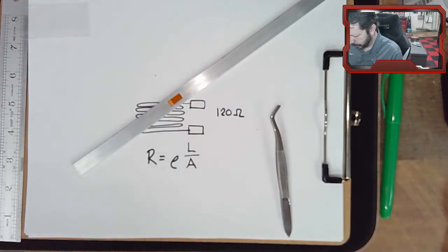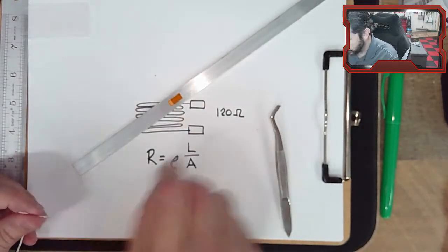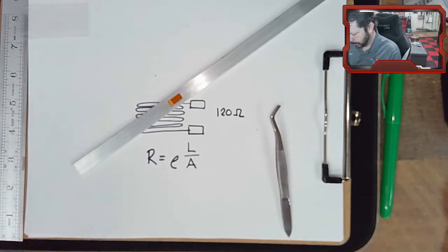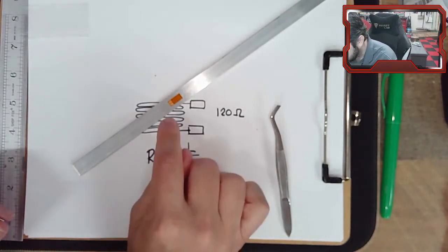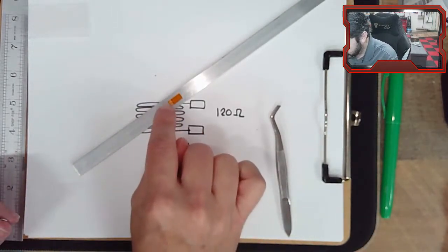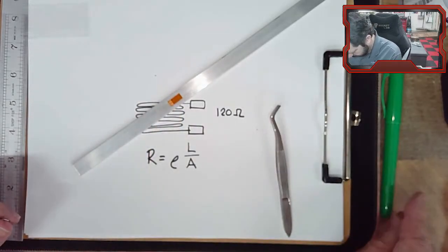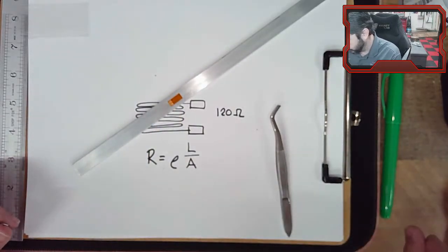This is the part, the soldering part, where you can make lots of mistakes. I guess the first mistake would be, if we glued this strain gauge upside down and we don't have any pads to solder to. That's kind of hard to overcome. You can sometimes, if you did that, scrape through the backside to get to the solder pads, but that's usually not going to work. But you could try.